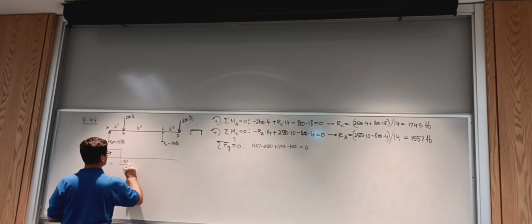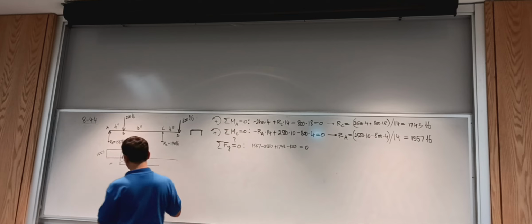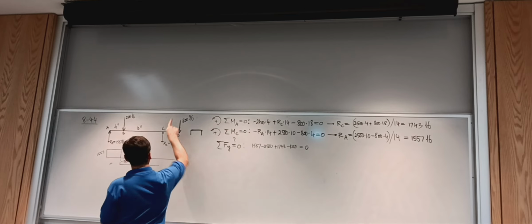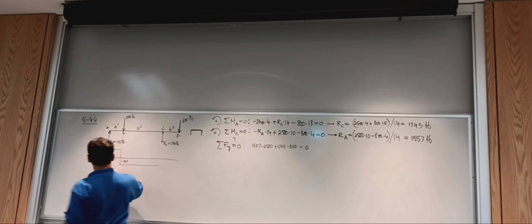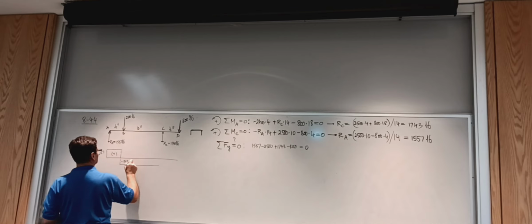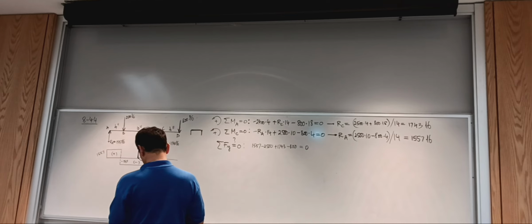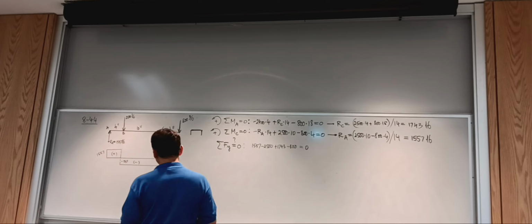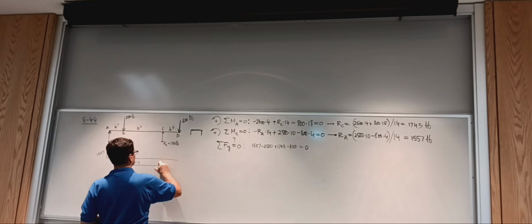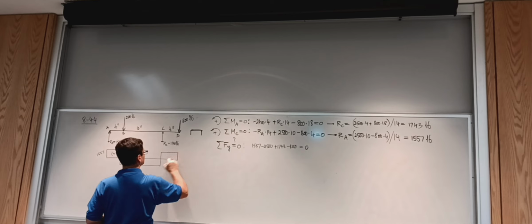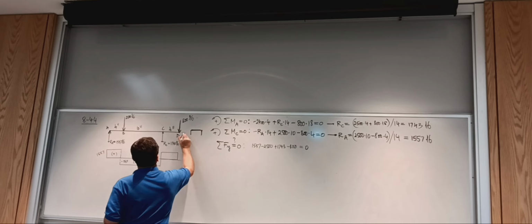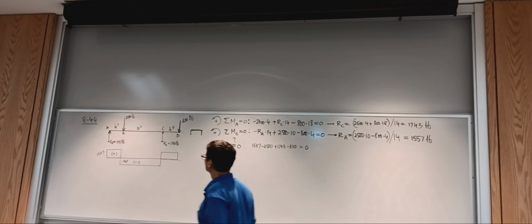And this stays unchanged, and then I have a jump up. Well, drop is down, jump is up by 1,743. So plus 1,743 equals 800, as expected, because the diagram will close to 0 once I pass point D. So a fraction of an inch left or right of D, I get to 0.